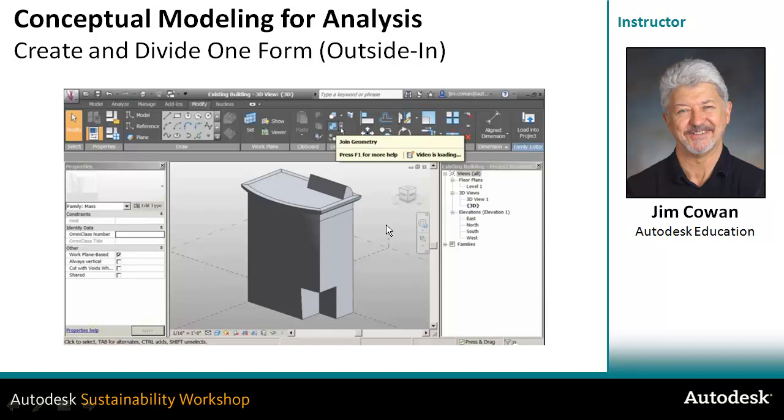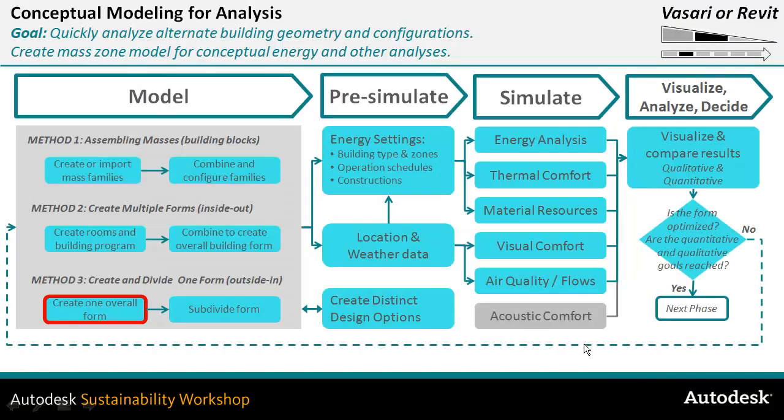But you know that you're not actually going to analyse that building, because if you analysed it, you're actually going to assign, say, the different surfaces of that roof things like percentage glass. So really what you're doing in this scenario is thinking about existing buildings that will provide the context, and it's appropriate to model them just from the outside in, as it were. So in that scenario, you're just creating an overall form because it's important for the energy study, not because it's the building being analysed, but because it's a building creating context.